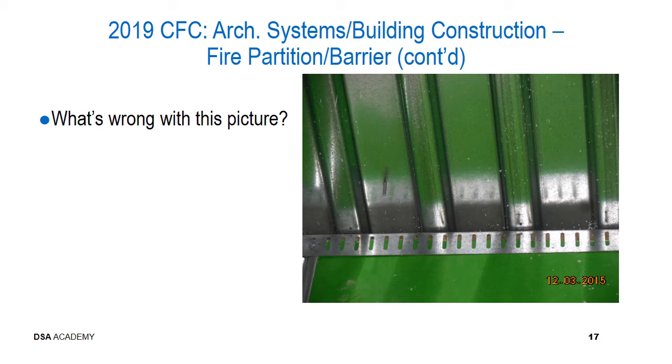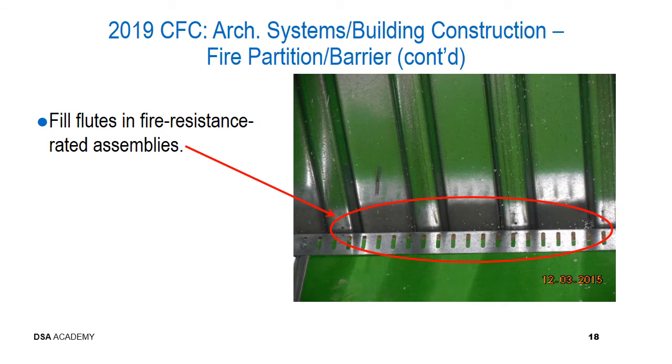Here's another example. Remember, continuity, protection of openings. The flutes in this condition must be filled with the material as prescribed in the fire resistance rated assembly detail.